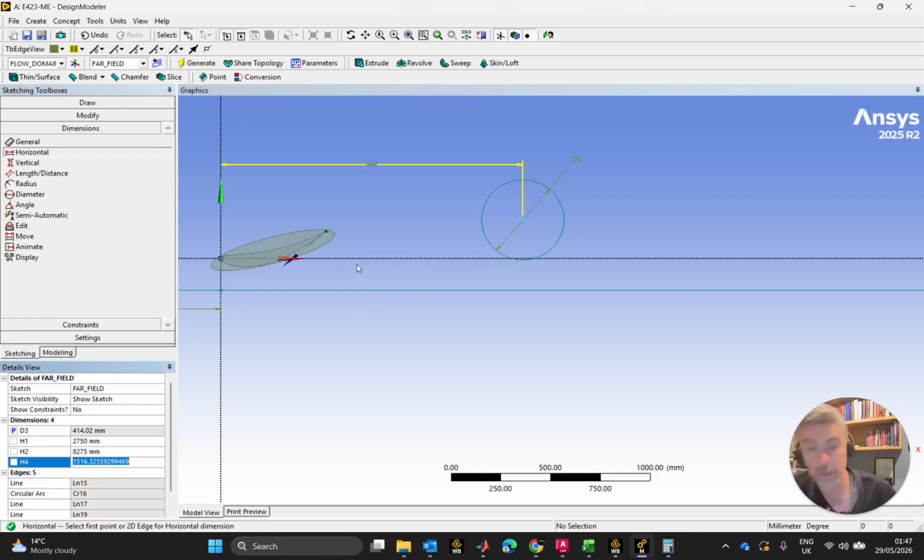So what distance should that be? Well, as I said, I know from regulation that the maximum distance between the front of the airfoil and this leading edge of the tire is 700 millimeters. So that's 700, and then the radius of that tire would be 207.01, would take me into the middle. So that leaves us 700 plus 207.01 gives me 907.01. That's going to pull my wheel and tire up to there.